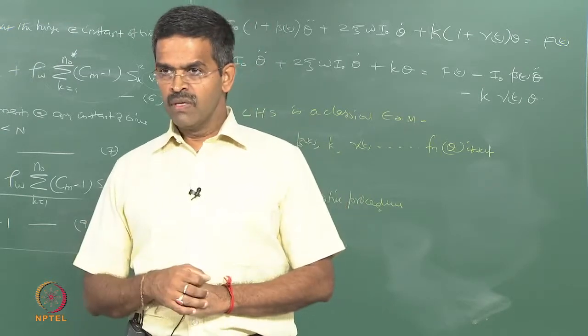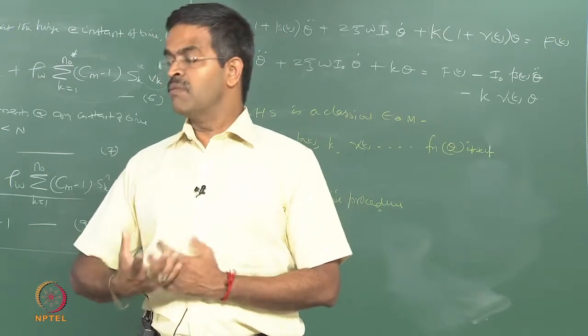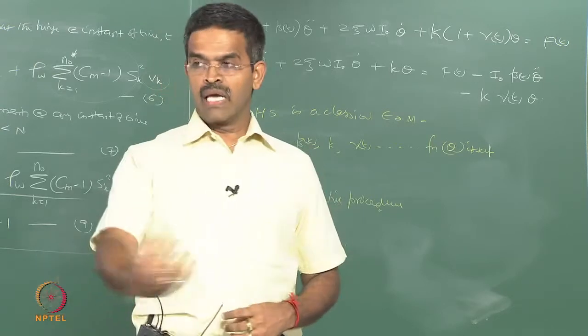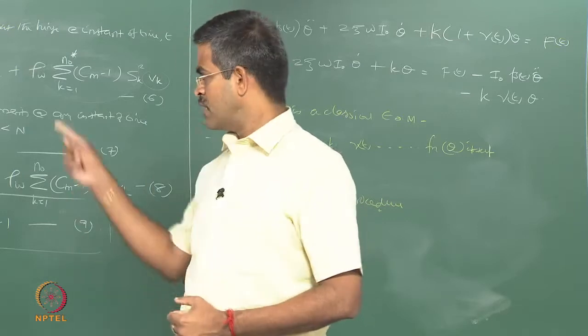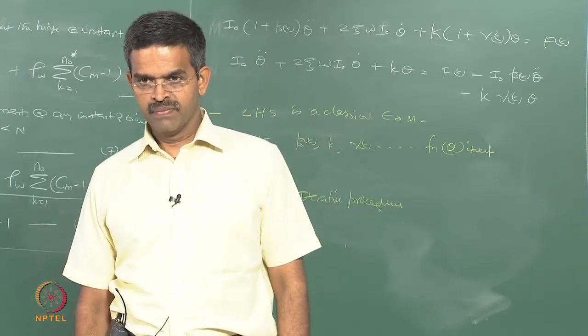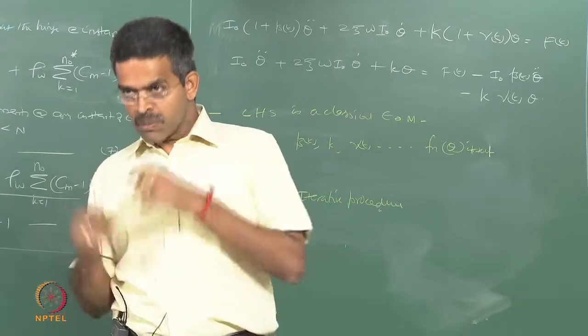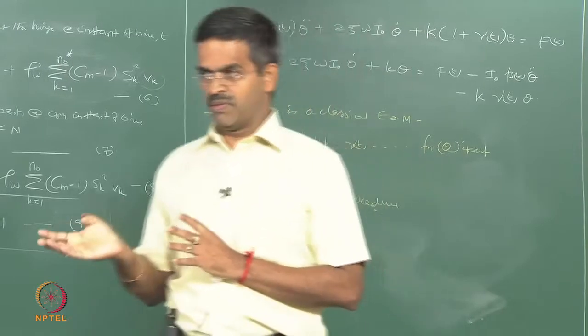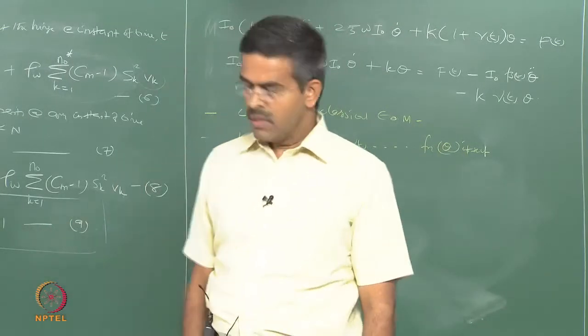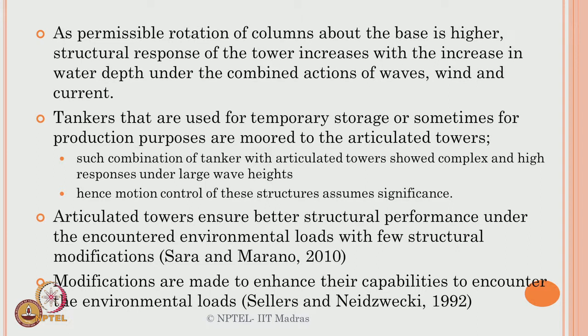very simple foundation, easy installation, better stability and enhanced deck area, more payload in terms of production facility, but it has shown larger responses. So, people said, can I work now on response control, can I control the response now, okay, because it is giving larger responses. So, the reason was the rotation permissible at the column became higher. Okay. The structural response therefore increased tremendously because of the rotation in combination of wave, wind and currents.